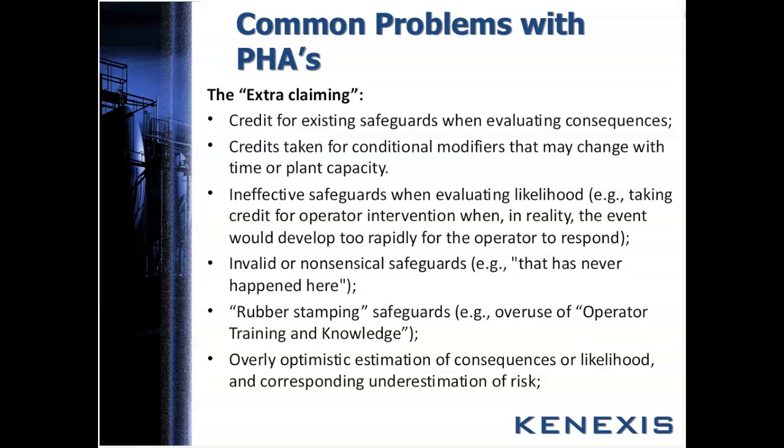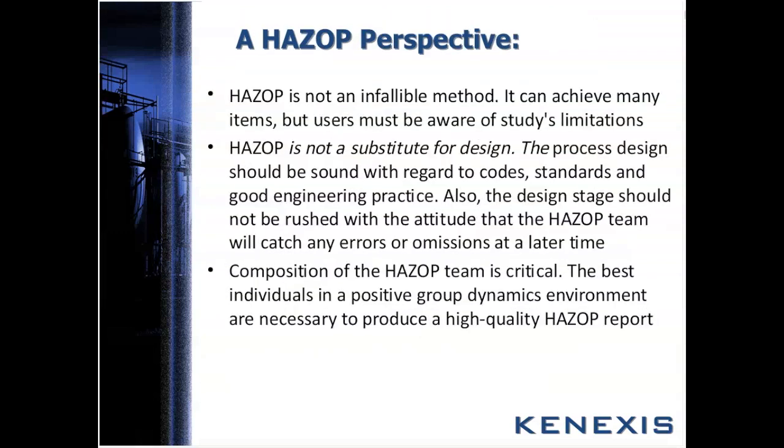Ineffective safeguards. An operator may respond to a temperature alarm and have some task, but he's got 6 seconds to do it when it takes him 15 minutes to analyze and respond to that. You don't take credit for those kind of things. Or excessive optimism in what might happen if you had a consequence. Okay? So a HAZOP isn't an infallible method. It's not a good substitute for design.